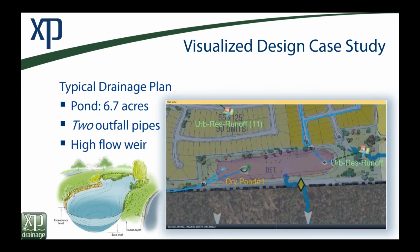So what would we need for this detention basin, being really our sole attenuation facility on this site? We would look at having a pond of almost 7 acres, with 2 outfall pipes and a high flow weir.